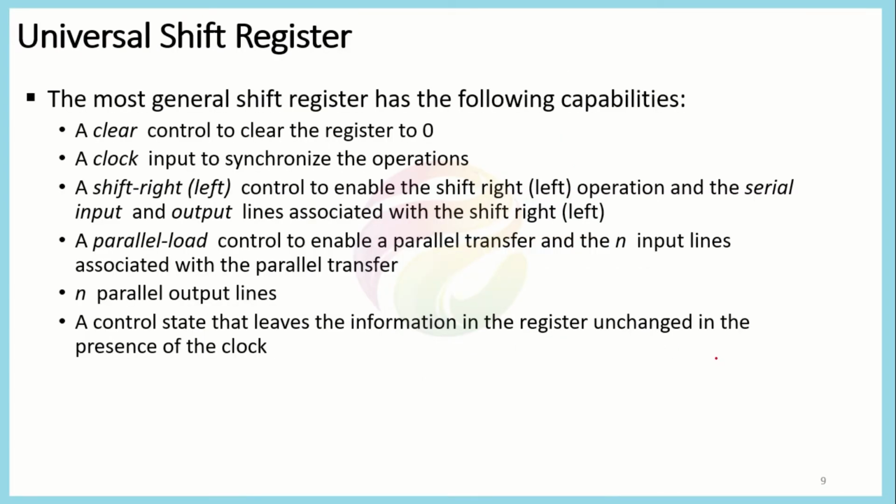Say we could add extra functionality to the shift register that we have discussed so far, in a way that we have an n-bit shift register which comprises, say, 3 different flip-flops, and we have accessibility to each output of each of the flip-flops in the system. Then we could also get the output in parallel form, because we are already getting the values in the form of a serial output, but we would also be getting the values in parallel too. So there could be an extra functionality added to the system.